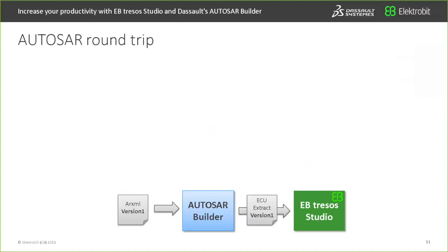What you normally need to do now is integrate into this existing data, which could be, for example, a software architecture with some software components provided by your customer, your own software components, and integrate them into your top-level architecture. At the same time, you usually get a communication matrix from the customer, which you need to integrate in terms of the data element to system signal mapping.